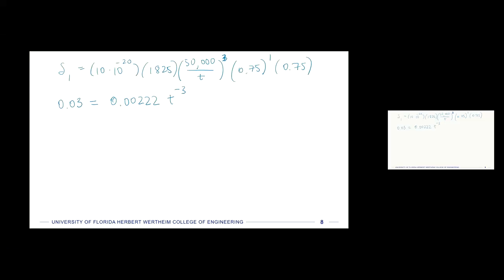And I forgot one thing in here to get that number. So we had a safety factor of 1.2. And if we think about our prior use of safety factors, they usually go on a stress, because that's usually what we're using as our framing for failure criteria.